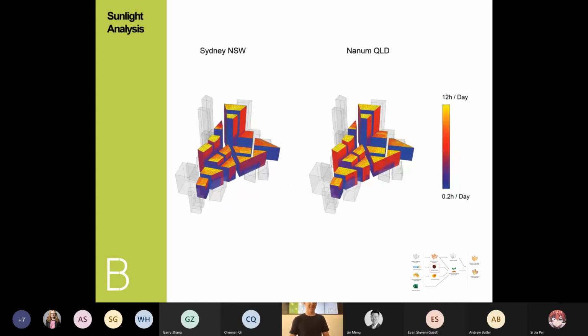Plants also need sunlight, but on an urban site with heaps of buildings everywhere, it's hard to know how much sun every bit of space is getting. Luckily, Energy Plus stores weather data into Energy Plus weather files. These files can be processed in Grasshopper with an analysis tool called Ladybug, which in my case was used to simulate sun paths and rays to find out how much exposure each grid cell gets per day on average.